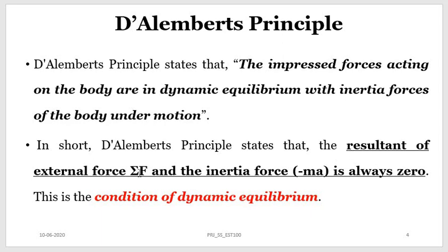Or in short, we can say that D'Alembert's principle is that the resultant of the external force sigma F and the inertia force, whose magnitude is minus ma, is always 0. And the equation sigma F minus ma equal to 0 is called the condition of dynamic equilibrium.